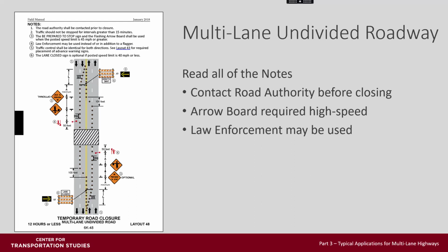Before closing a roadway, even for a short period of time, make sure you have the proper authorization from the road authority before doing that closure. The arrow board is required on a high-speed lane closure, and law enforcement may be used.